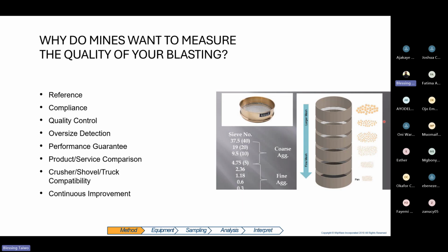Then you want to assess what goes through your crusher and what will not impact your stability. All the software does for you is to pick the whole of the material, just like your sieve analysis in the lab. You pass the whole material into sieve classes. In this case, the software is passing the whole material through 25 sieve classes. So it's like you're having 25 sieves set upon each other, and the whole of the blasting is passed through it. And like the lab, you have to keep checking.